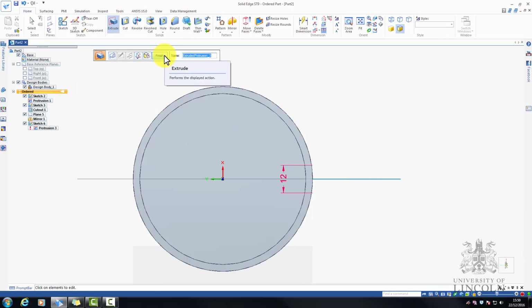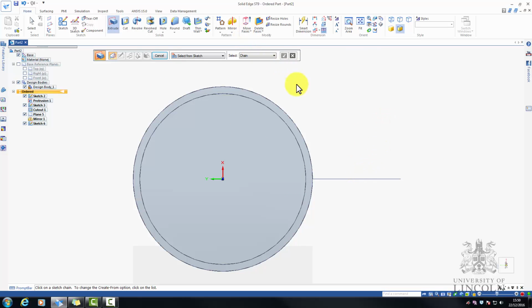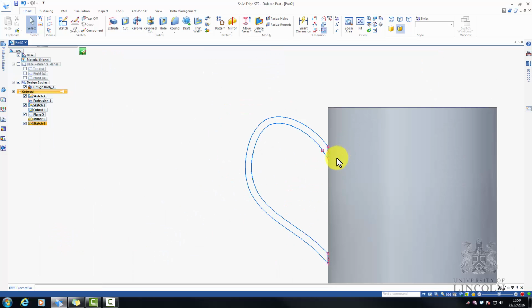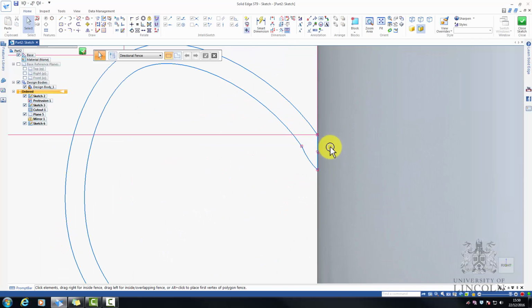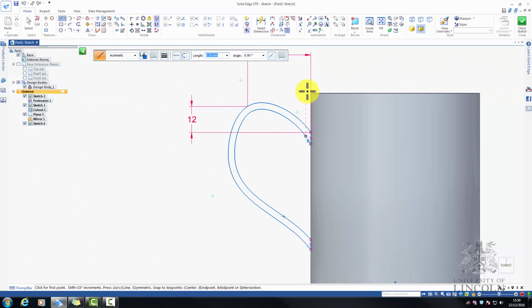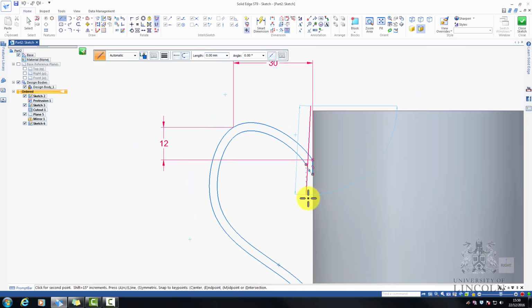So this is a bit of an issue. It's something that commonly happens when you're trying to extrude a linear extrusion onto the side of a cylindrical existing projection. So with that problem, I'm going to go in and edit the profile. What could I do? Well, there's a few things I could try to do. I could either think more carefully about how I create my extrusion in the first place. I could recess and remove material. So I could create a line that runs down like so.